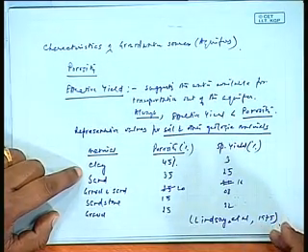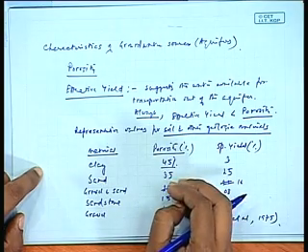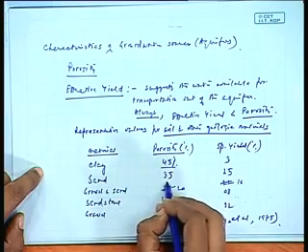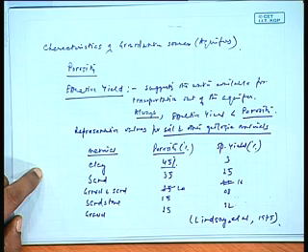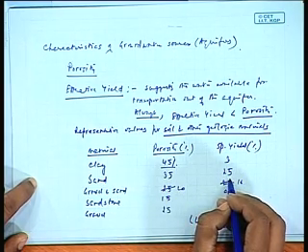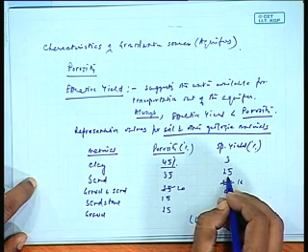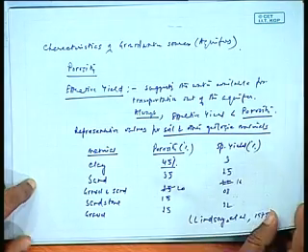What is understandable here is that clay can contain about 45% of its volume as water, whereas sand can have about 35% of the total volume as void that would contain water. So the available water is 35%, but only the transportable water, the water that can be drained out, is about 25%. The rest of the water would be locked into the structure itself, either in the form of vapor or in the form of water. This is what is meant by these two terms, porosity and specific yield.